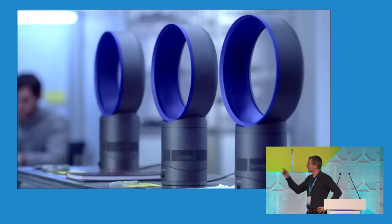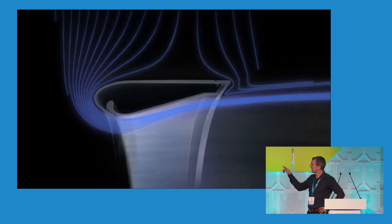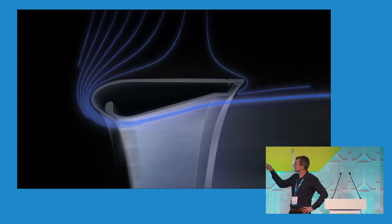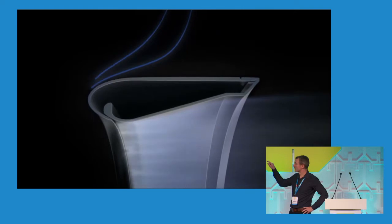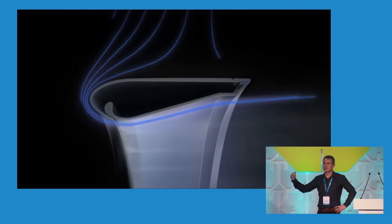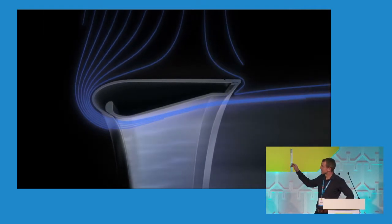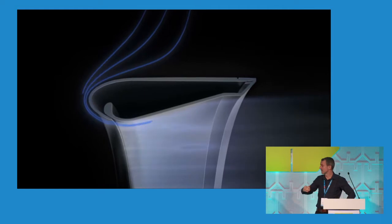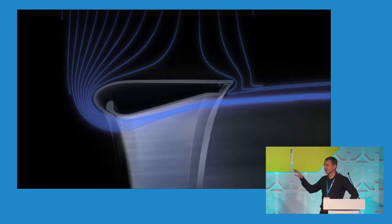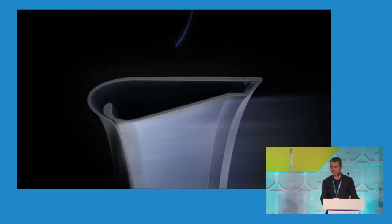We use this effect on our products. As Paul mentioned, this was a quick clip from one of our early fans. And you can see what's going on here is that the air is exiting through that very small slot towards the rear of that image. But it's entraining a huge amount of air with it. And that's what those blue lines represent. So it's actually pulling the surrounding airflow along with it. And through that, we can get multiplication of the amount of airflow coming out of the product, which I'll come on to a little bit later on.